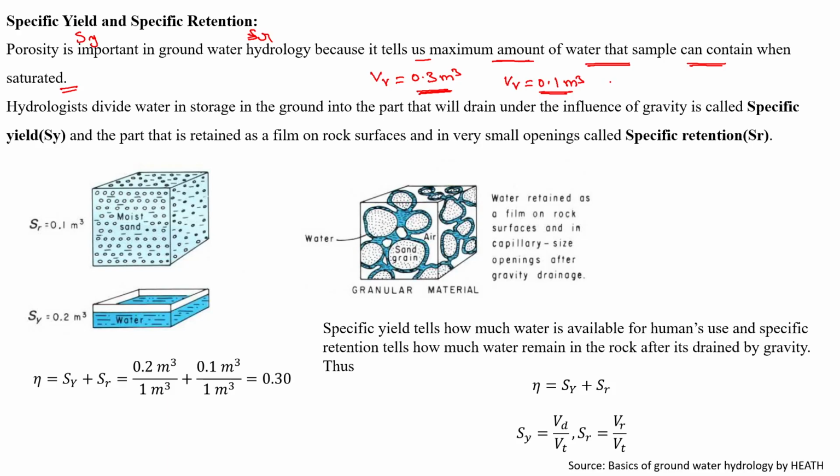In that case, we should know how much water to supply. Whatever water we supply to the field does not always infiltrate, and does not always make the soil saturated. So we should calculate the total amount of water required to make the soil saturated in irrigation planning. That is the significance of porosity, which is very important in irrigation planning and geotechnical engineering.